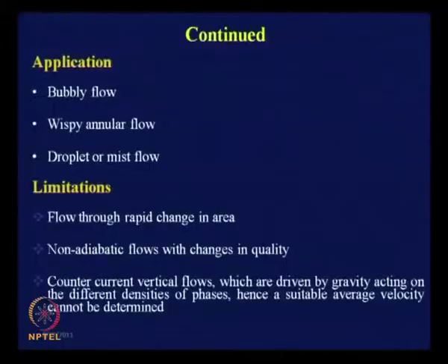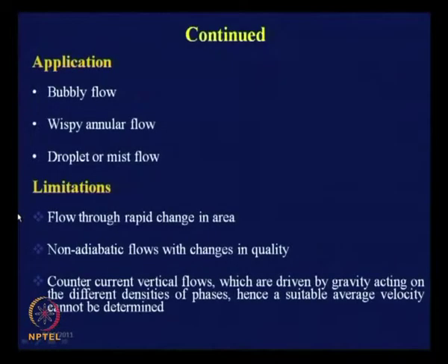Under this rapid acceleration, then we cannot have the two phase flow situation. This I have already written down here. Okay. So, this is one thing where we cannot have it, and for the rapid acceleration, what is the problem? Let the two phases accelerate. Why cannot we use it? Because under such circumstances there is a drastic change in pressure. Moment there is a drastic change in pressure, flashing occurs. Moment flashing occurs, thermodynamic equilibrium is no longer valid. Clear to all of you?